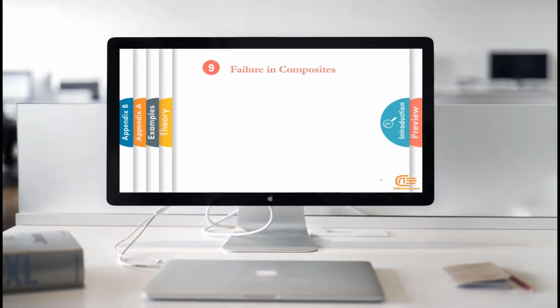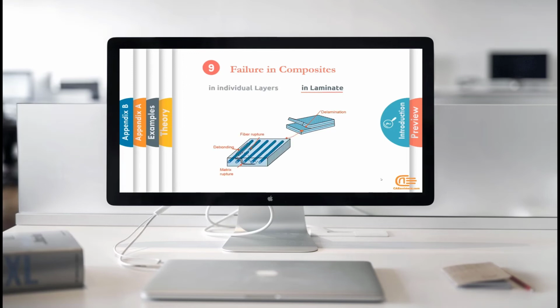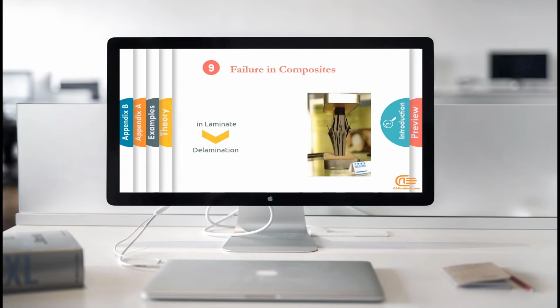A composite laminate can fail in two basic failure modes. The first mode is that the failure occurs in laminate due to interaction between layers, which is actually called delamination, as you know. In the second mode, the force of tension or pressure or shear causes the failure in a ply of composite individually. Stress experienced by the composite initiates cracks and causes delamination between the laminates and leads to more severe damage.